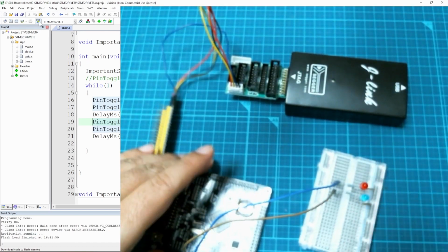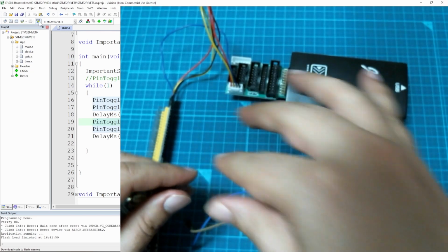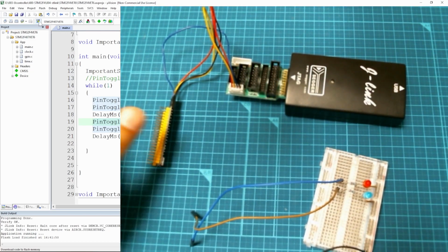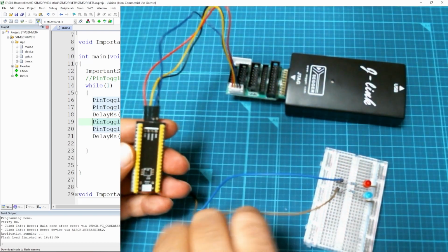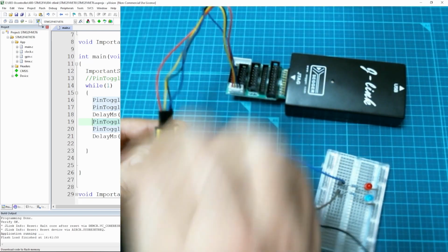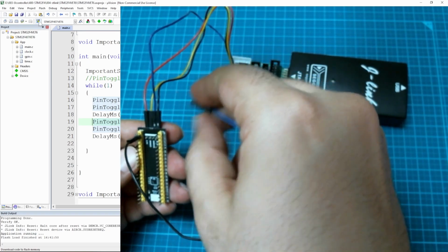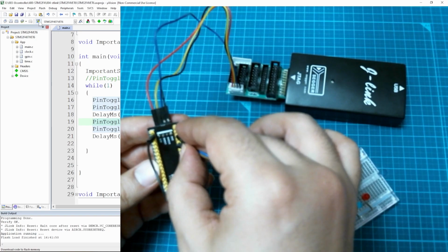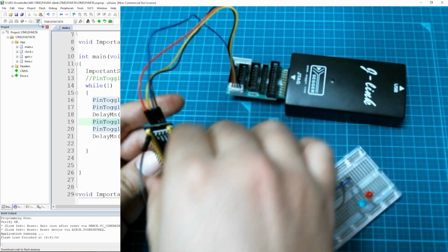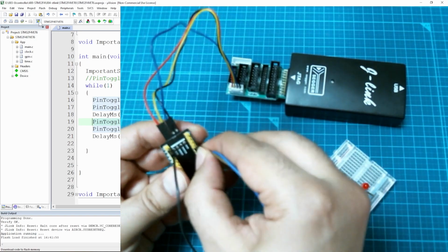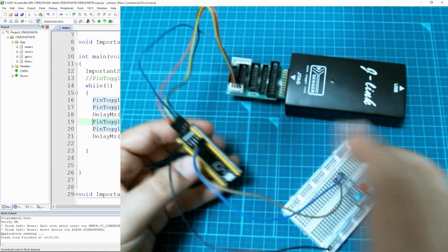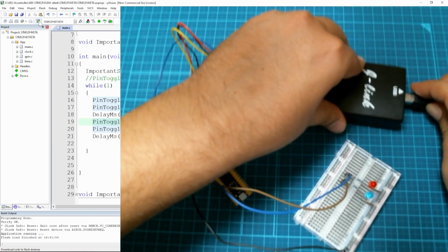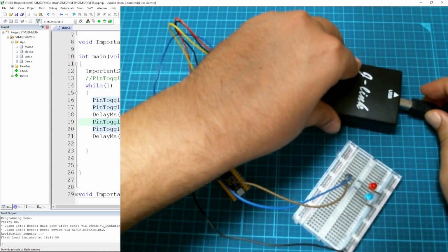and let me get this one like this and connect it before connecting the whole thing to power. So this one should be connected to ground, where these two little ones will be connected respectively to A0 and A1. A0 and A1 are always near each other. Perfect. So let's power the whole thing and see how it works.